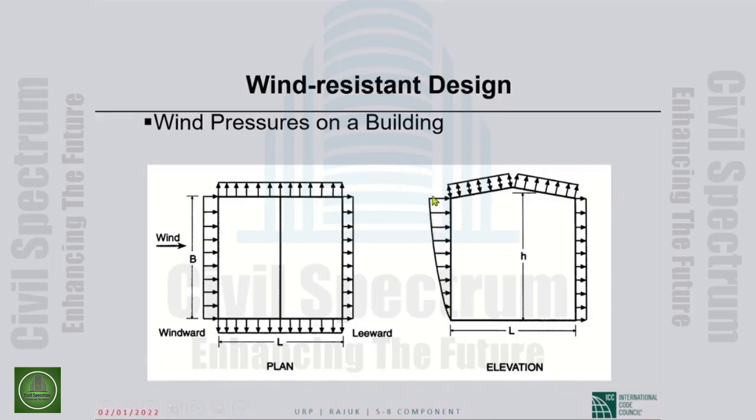we recognize only on the windward face of our building. On all the other faces, the leeward face, the side faces, the roofs, we go for a constant suction evaluated at the mean roof height level.